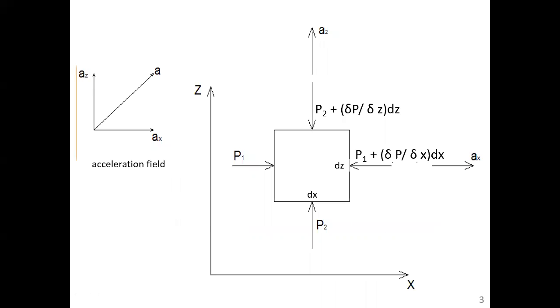So we start at the exact same place, and this is all on your handout, that we did with fluid statics. We are going to start with a differential sized cube, and the cube is dx by dy by dz. But instead of looking at a three-dimensional derivation, we're going to look at a two-dimensional derivation, just like we did before, and say that whatever happens in the x happens in the y, since they're both horizontal coordinate axes. Because z is collinear with gravity, that is distinguished separate from x and y.